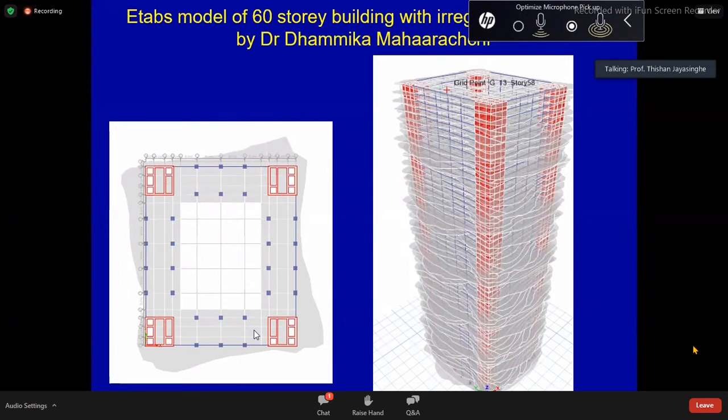And based on that, we proposed having 1.8 or 2 meter diameter piles under each column. And then you will ask, how about the spacing? These column spacings are about 9 meters, 10 meters. So there will be plenty of space for having four large diameter piles.